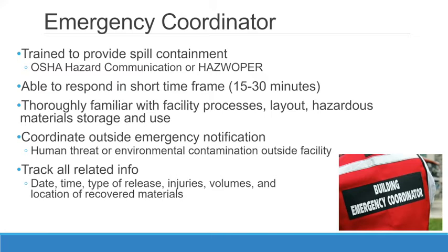Again, depending upon the nature of the amount of material you have, OSHA now becomes involved, whether it's a HAZWOPER requirement, hazardous waste operations, or even HAZCOM. Basically, the rule of thumb is OSHA says if the spill or release can be cleaned up with the people in the immediate area, then training under hazard communication is sufficient. If that spill or release is much greater quantity, then I need to go in to have formal training under the HAZWOPER program, and I think Mike has a slide on that, which we can touch upon.